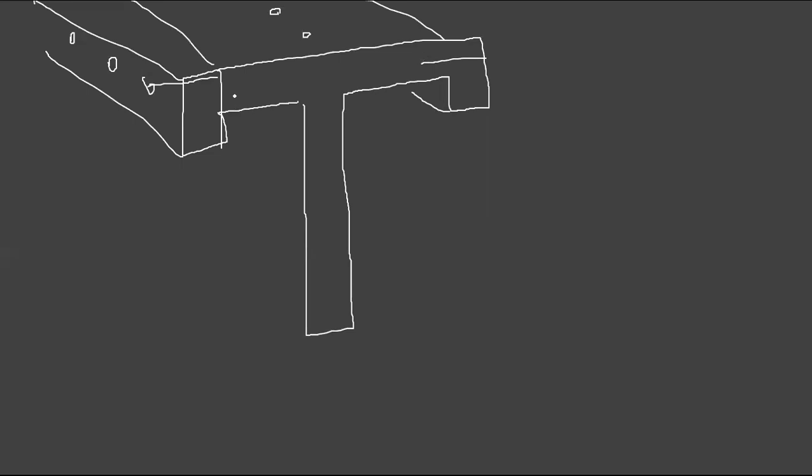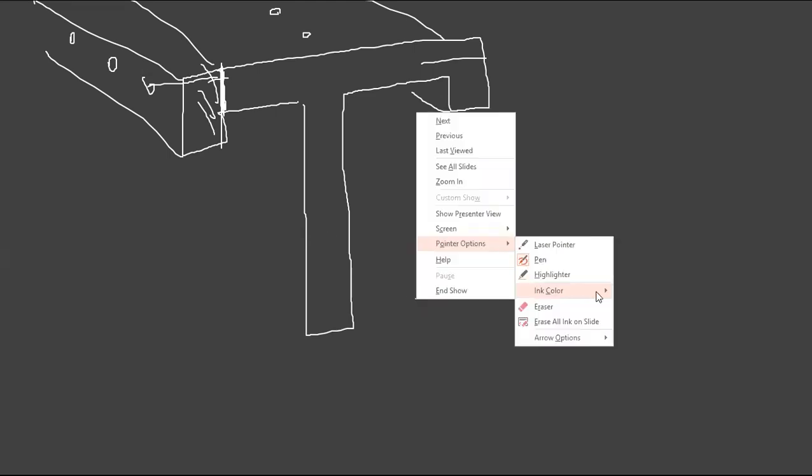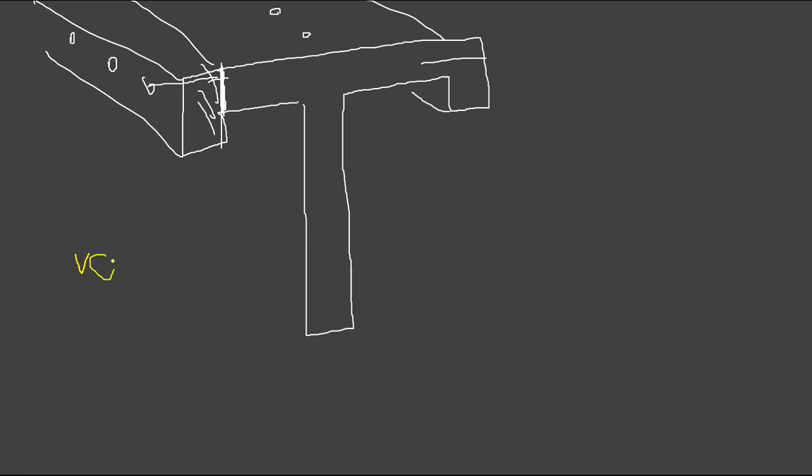In a similar way, this can fail with respect to this surface, so you have to find the shear flow at this location. You can find the first moment of area, and you know the shear force. That's child's play. You know I, you know V. The problem is Q.